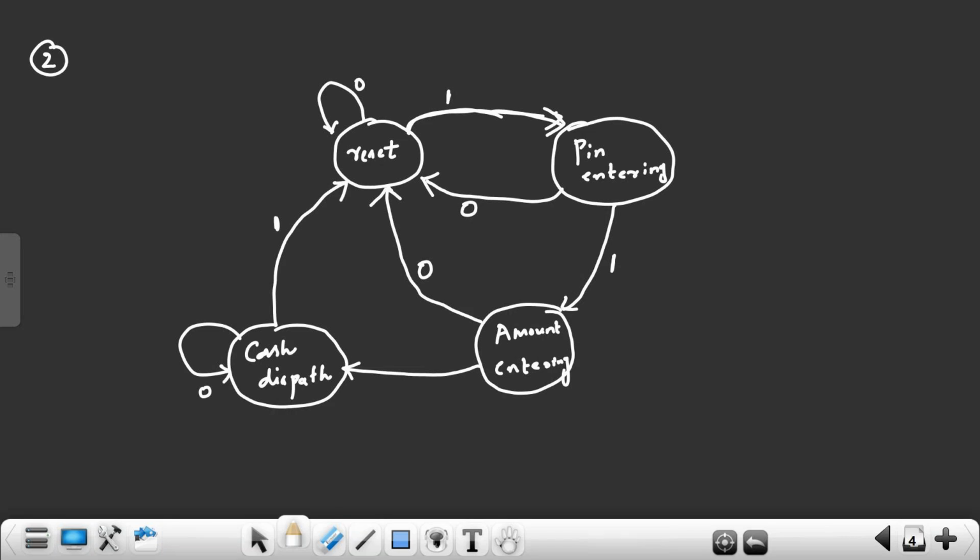Right. So now, I have just written a small diagram. This is called a state machine diagram. So a bigger circuit also we will divide into different states. Now we'll start writing the Verilog program to implement each state. For bigger programs we generally start with bigger designs. See, here also I am implementing the design by the behavior of the ATM machine, how it is going to behave. So for this again I'll start writing the Verilog code to implement each state.